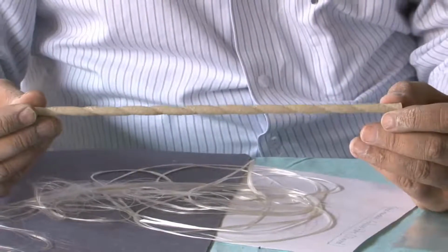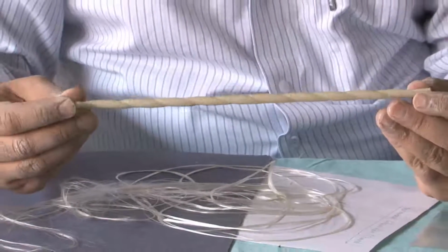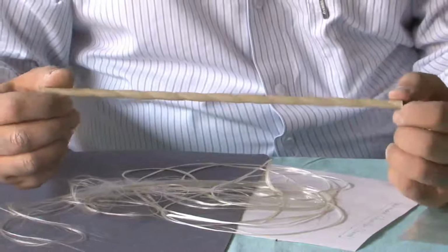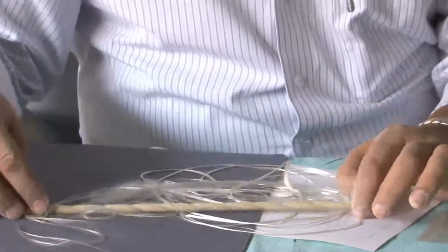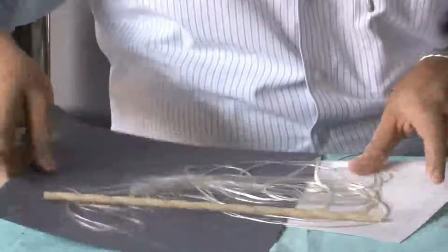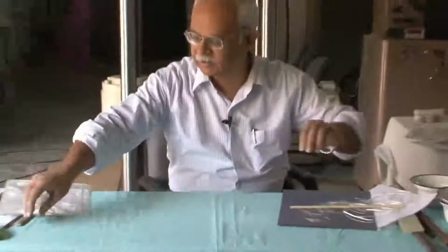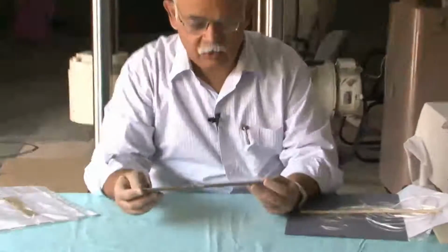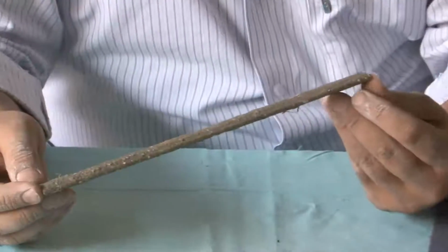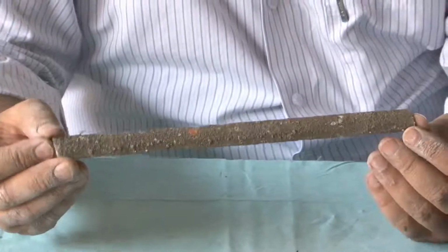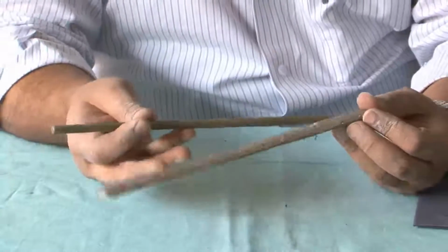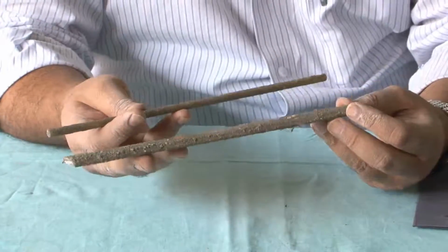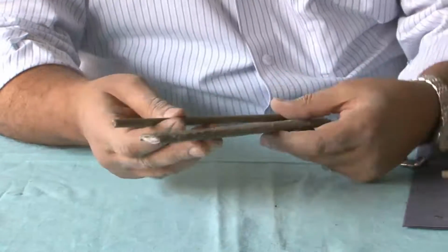And on this bar you would notice that there are corrugations to improve the bond between the concrete and the reinforcing material. Another way of improving the bond between the reinforcing material and the fiber reinforced plastic could be sand deposits. So, we make some effort and deposit sand or create roughness on the surface of the bar, so that we get a better bond between the reinforcing material and the surrounding concrete.